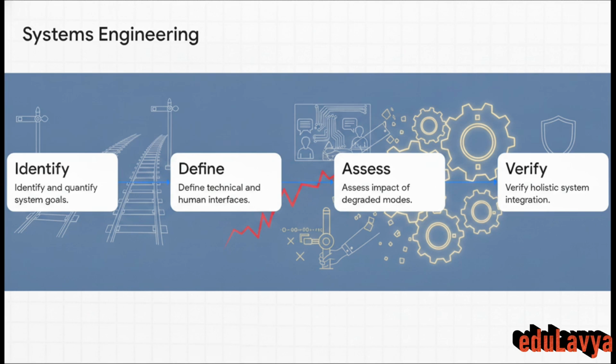Let's pause on step 3 for a second. We have to ask ourselves a really critical question. What actually happens when a telecom network fails? Suddenly, the automatic routing drops out. The signals might automatically revert to a fail-safe danger state. And at that exact moment, the technical system steps back, and the humans, the signalers and the drivers, have to rapidly intervene. The whole interface management process has to anticipate this exact kind of scenario.